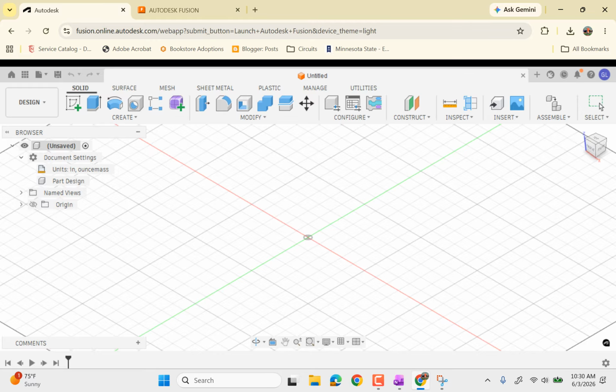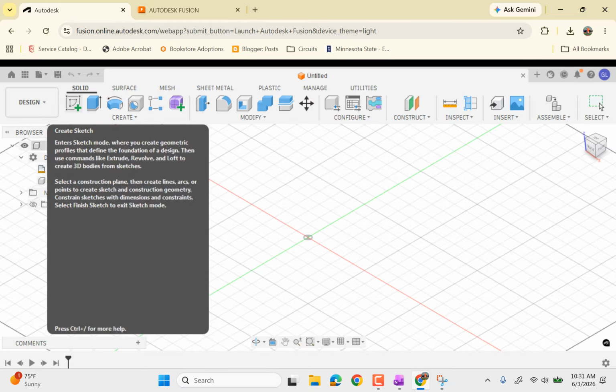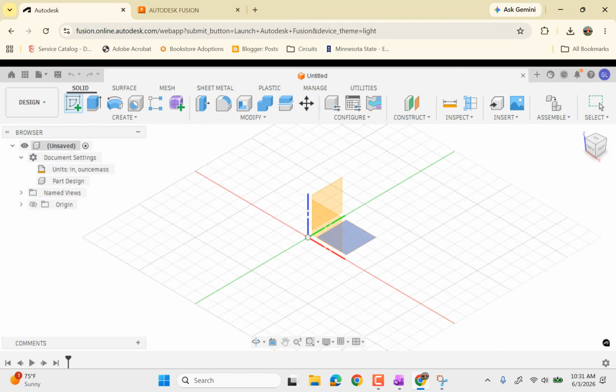Okay, and so we're going to sketch this shape with the sketcher, the same one that we use for extrude. And then we'll go to the revolve for that shape, and we'll have to tell the computer what the axis is we want to revolve it around. This shape would look different if we revolved it around a different axis. And then you'll see that that shape pops in there. Okay, so I'm going to go to the sketcher, choose a plane to draw this in.